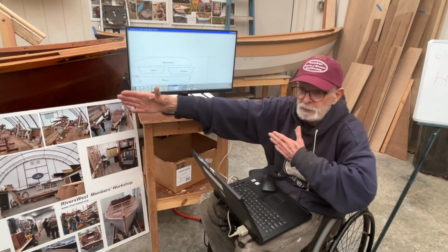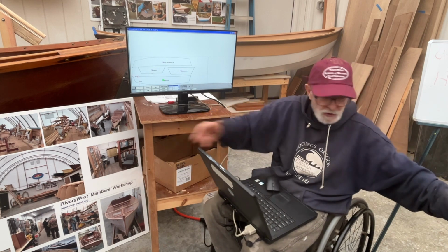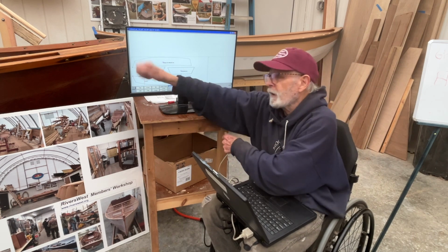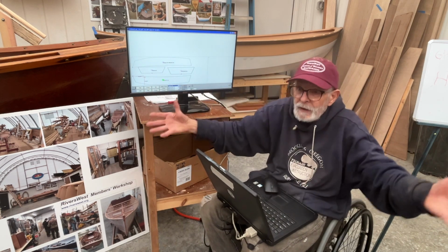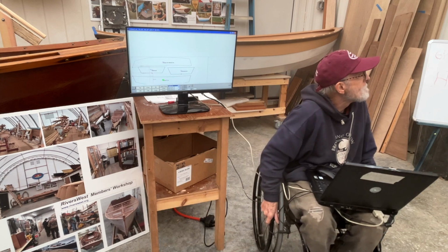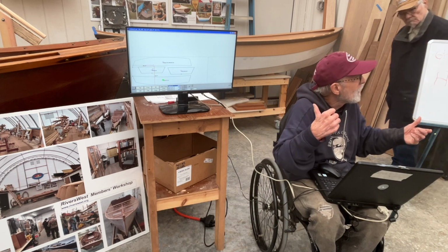And then you take your sheet of plywood, take a drywall T-square, put a tape measure across, come over 15 inches, mark X, X, X, X, spring a batten, and now you've got your exact pattern. So you have to create that list yourself, it's not going to produce that.